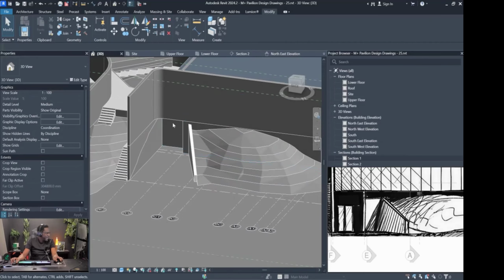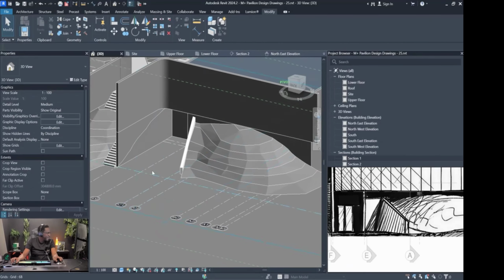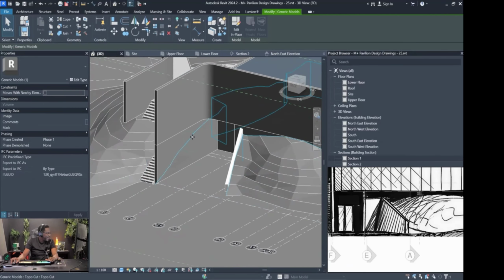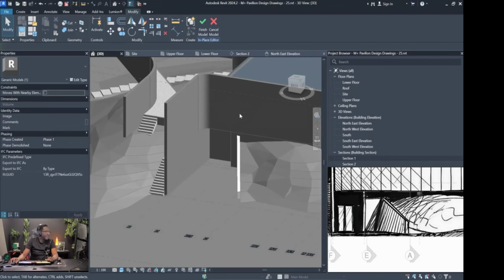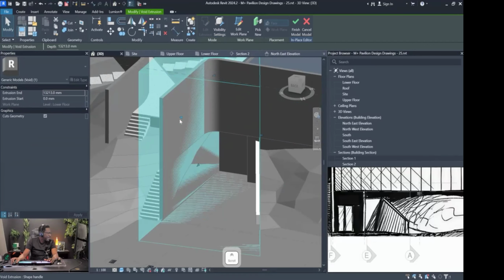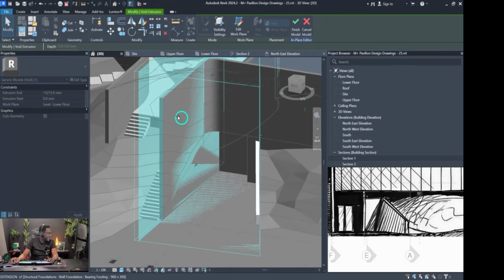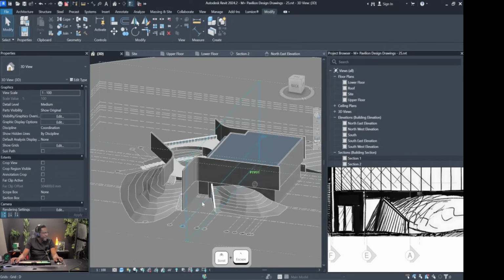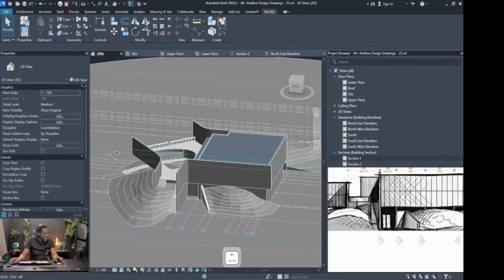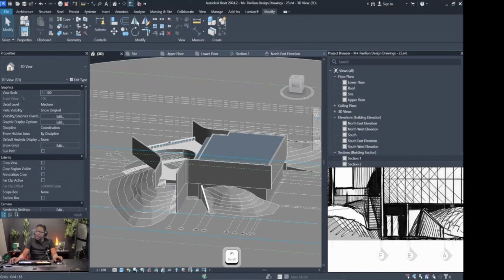And we know that we will end up with a door in here. We have a weird line here, which is because of how the void form is cut. So let's edit that again. And we're going to push this out to this face. Yeah, there we go. All right, looking good. So now we can see this area here is looking more like this area here.